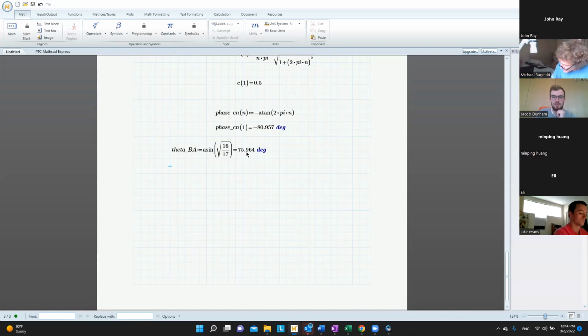We know that this is going to be equal to omega times square root of mu naught epsilon naught times the sine of the incident angle is equal to omega times square root of mu naught epsilon naught times square root of mu relative epsilon relative in region 2 times sine of the transmitted angle. We can see a whole bunch of this stuff cancels.